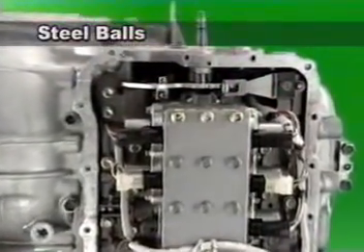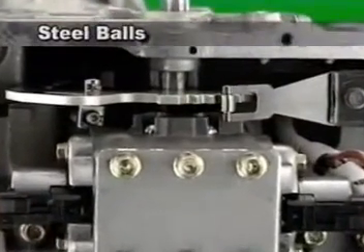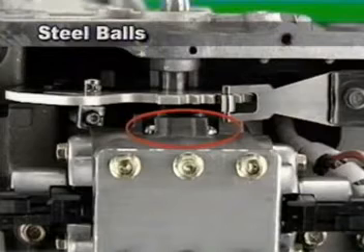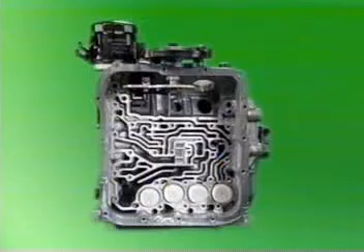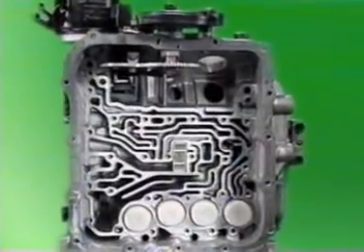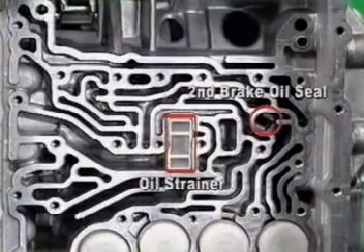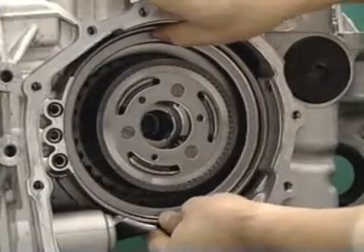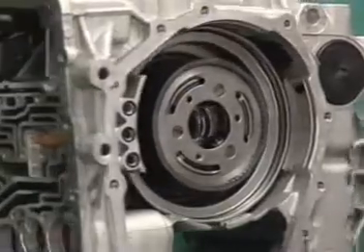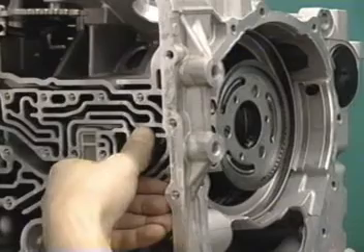2 steel balls are inserted at the upper part of the outside valve body, which function to shut off the drain hole by gravity. Be careful not to lose these 2 balls in assembling or disassembling. Now for the strainer and second brake retainer oil seal. When reassembling, the second brake retainer should be assembled before second brake oil seal. This procedure prevents oil seal damage.